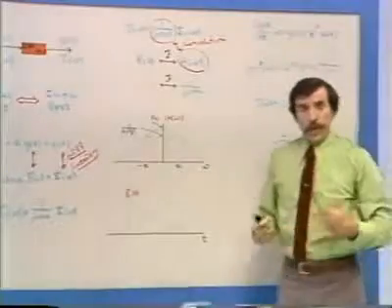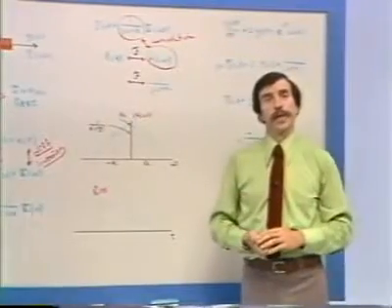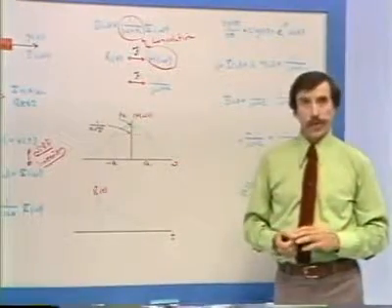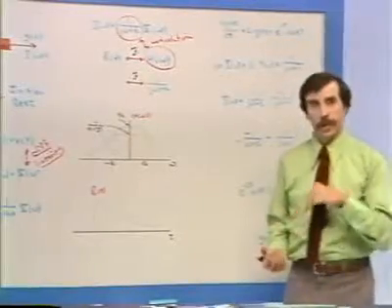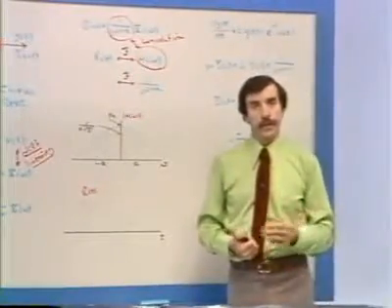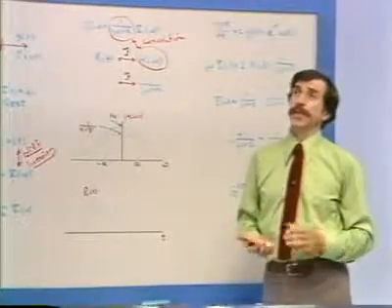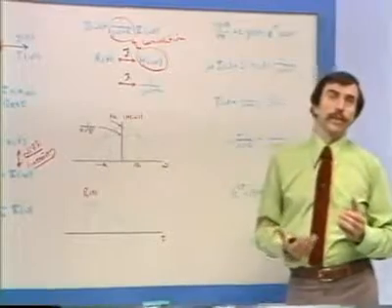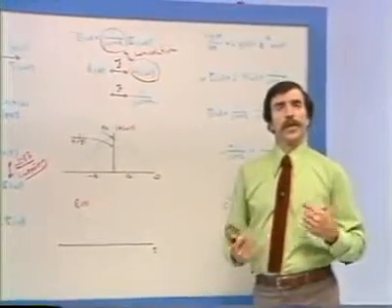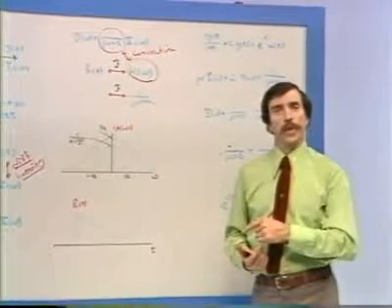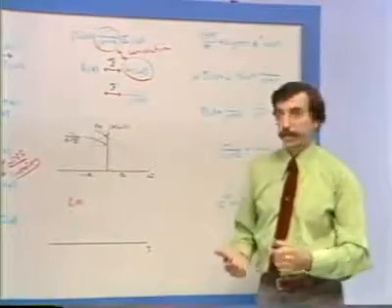Now, we may have, for example, wanted in our problem, instead of getting the frequency response, to get the impulse response. And there are a variety of ways that we can do this. We can attempt to go through the inverse Fourier transform expression. But in fact, one of the most useful ways is formally called the inspection method. Informally, it's called, if you worked it out going one way, then you ought to remember the answer so that you know how to get back method.